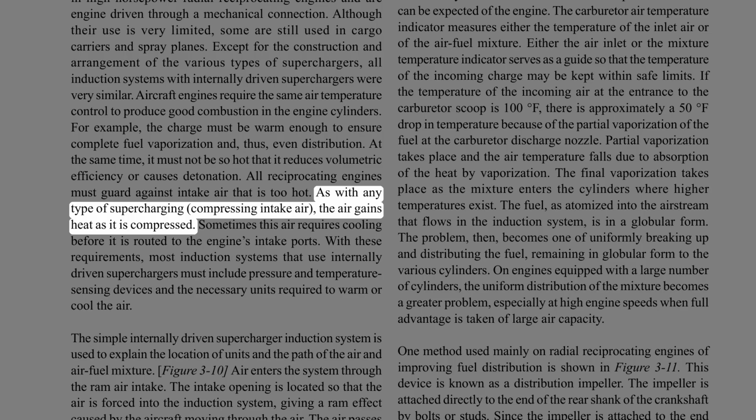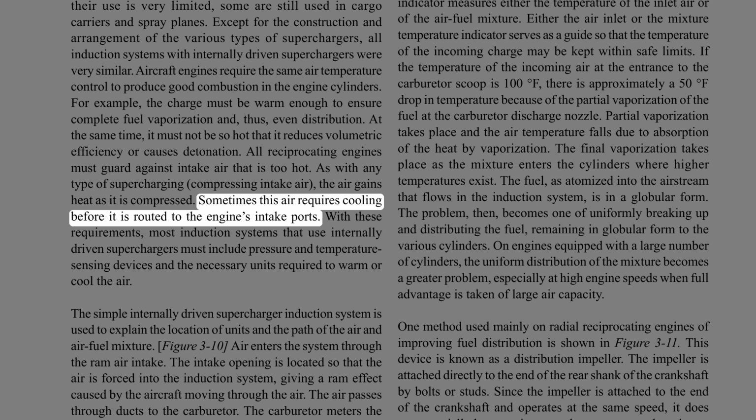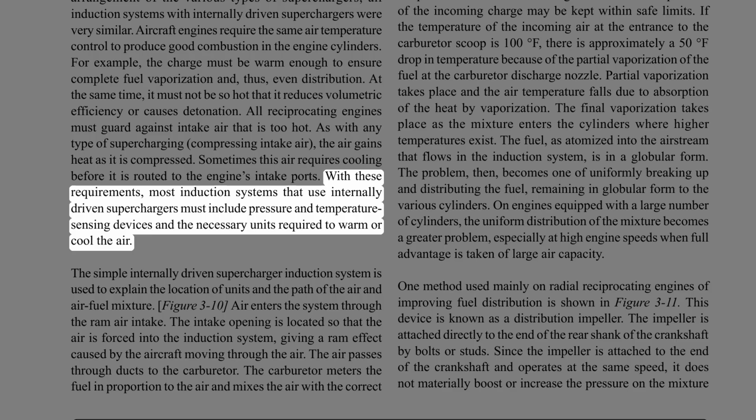As with any type of supercharging, compressing intake air, the air gains heat as it is compressed. Sometimes this air requires cooling before it is routed to the engine's intake ports. With these requirements, most induction systems that use internally driven superchargers must include pressure and temperature sensing devices and the necessary units required to warm or cool the air.